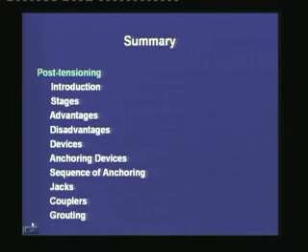Another equipment we have learned about is the grouting equipment. Grouting is an important stage of post tensioning, where we ensure that the grout is of good quality. It will provide an anti-corrosive environment so that it will check any sort of corrosion of the prestressing tendons. Also, the grout will be strong enough to transfer the prestress between the tendon and the concrete. The grout should be strong throughout the service life of the prestressing tendon.